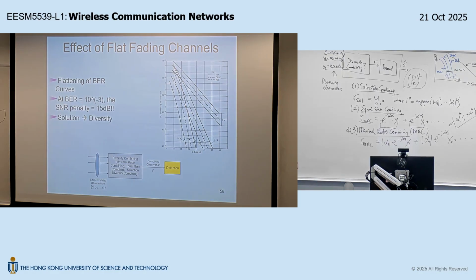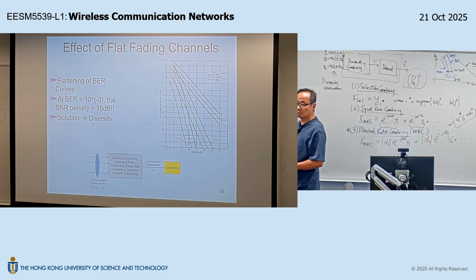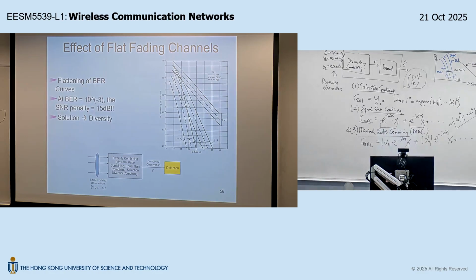The question is the same as asking, do you have an RF switch, right? It turns out there is a low-cost RF switch. It's called a PIN diode, okay? If you work on RF circuits, you should have heard about this. So there's a low-cost switch in the RF front end as well. Now, if that's the case, then I don't need to implement it here, which is an expensive solution. I can implement the selection up to here, right? Now, if I implement the selection up to here, then my entire data path could be like this.